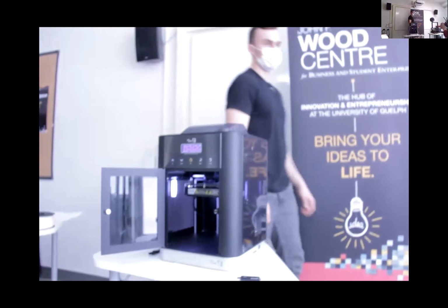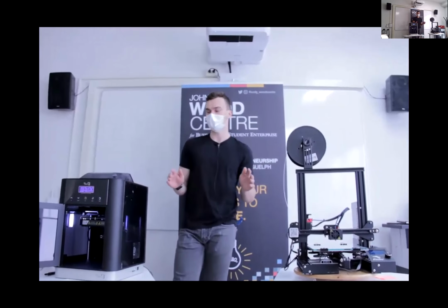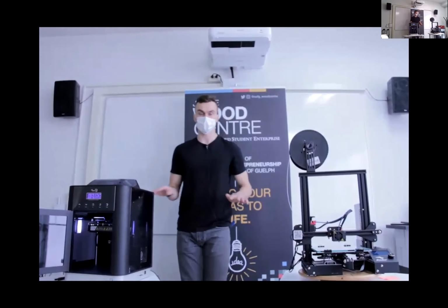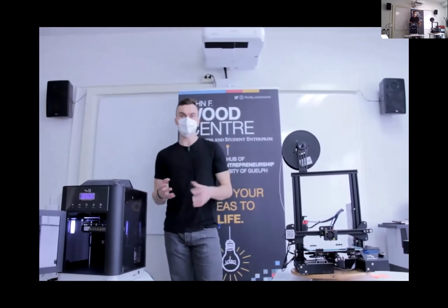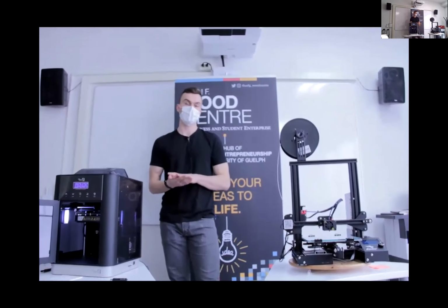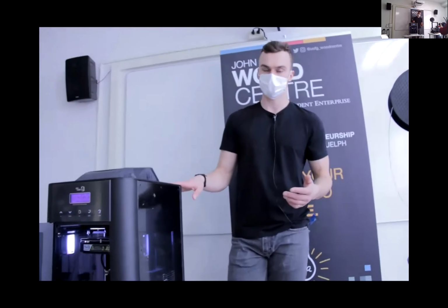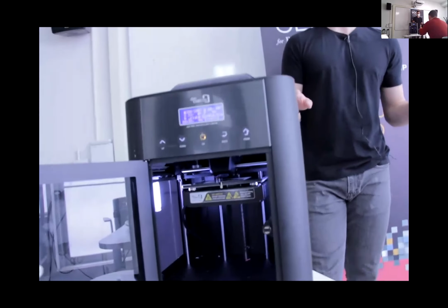So one of the questions was, can we leave it overnight for a very long print? Yeah, you can definitely leave these once they start going, as long as you feel comfortable with it. The most important thing is to make sure you watch that first layer go down. Once that first layer goes down, you know that the foundation of your print is adhered to the build platform, and it's less likely that it's going to become detached in the middle of printing. So as long as that first layer goes down, you're probably good to leave it to finish.